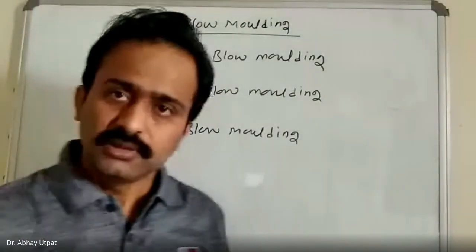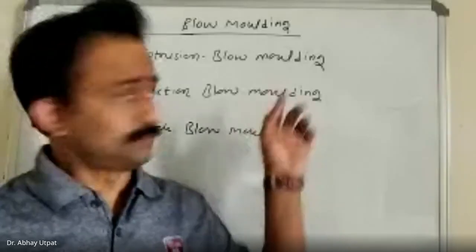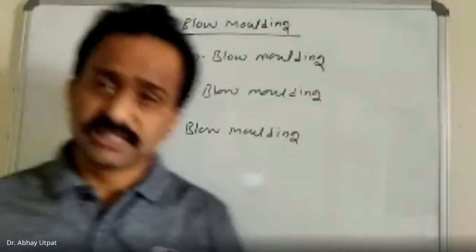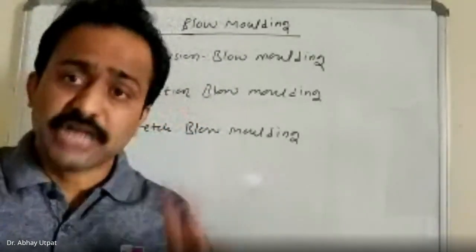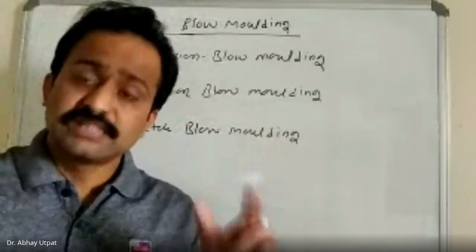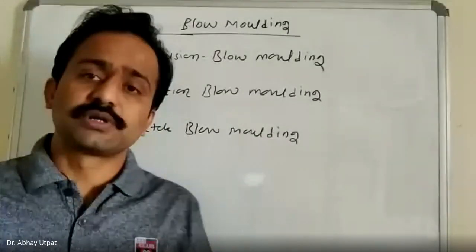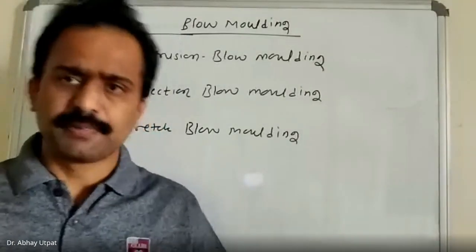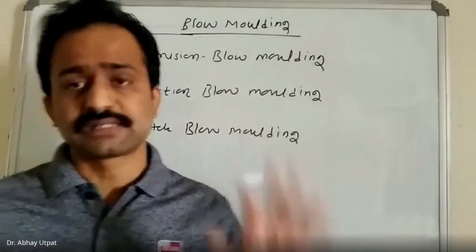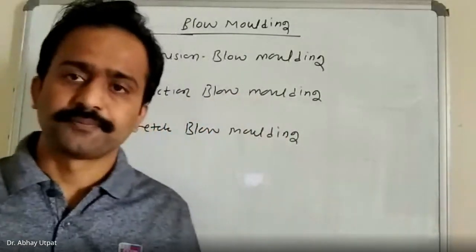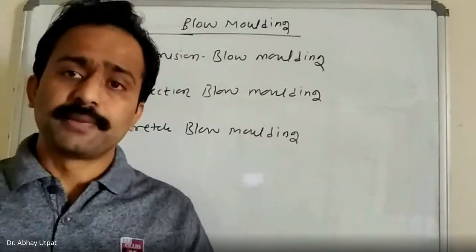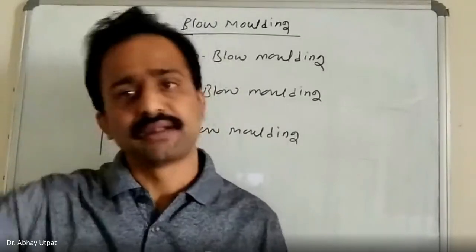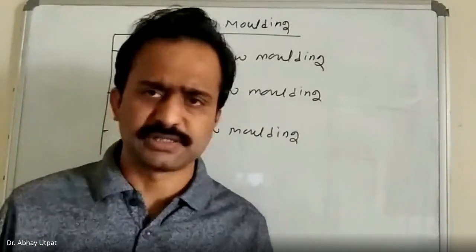So the bottom line, the blow molding process consists of inflating, swelling, of the plastic parison or preform into the closed die, so that the plastic will stick to the inside walls of the mold, and after opening the mold it will take the shape of the mold. Hollow products are produced, such as jars, bottles, and similar products. Maybe automobile manifolds and similar products. Best applications are different types of jars, plastic bottles of different shapes. By swelling into the mold, different hollow parts can be made, used for machine handles, handle covers, and other similar products.